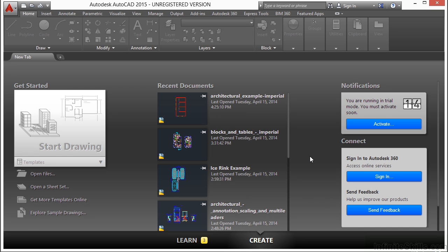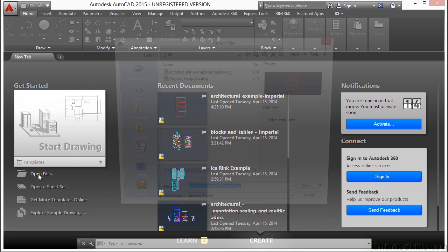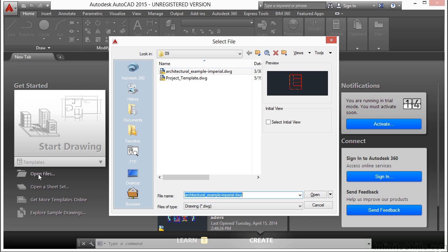Perhaps one of the biggest issues when creating drawings on a computer is making sure that they turn out the way you want them to on paper. This is where good layer management and use comes in. The purpose of layers is to organize the data in your file so you can work with it and so that it has a correct visual display on paper, not just the screen. We've already kind of mentioned this before with talking about the different viewports that you can use.